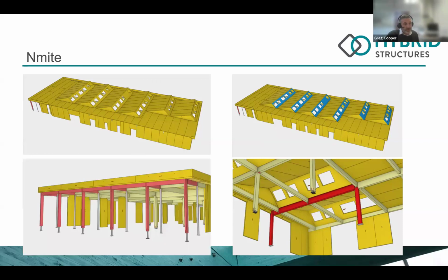And the third thing we touch on is the larch at the front. Now, he very eloquently discussed how that all works, but the other thing as well, we spent a long time talking to the team about the maintenance of these in the long term. Yes, larch was chosen, but the larch will still need maintenance over its life. So the whole structure in this canopy was designed to be able to be propped and potentially remove the columns and quickly replace them without significant impact on the usage of the structure.